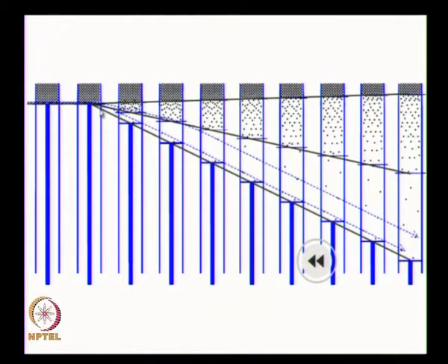What this means is, as it is increasing, I can now say that if my flow is supersonic, you remember this from long back, we said that if there is area change, if the incoming flow is supersonic and the area is increasing, we are going to have higher Mach number. That can also be seen from inside here if we think about the streamlines as stream tube walls. That is the extra information I wanted to give here in this particular expansion fan example.